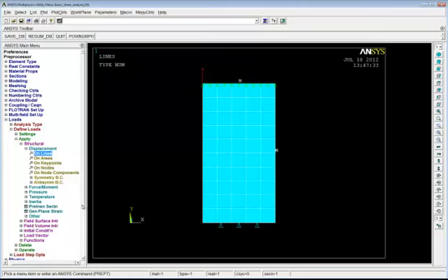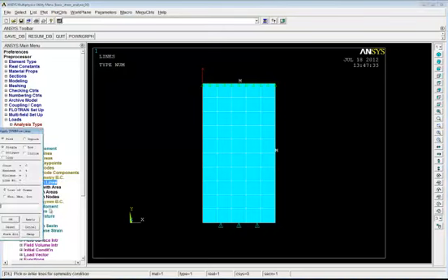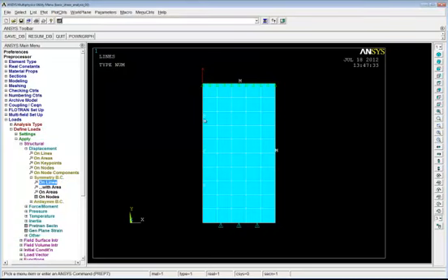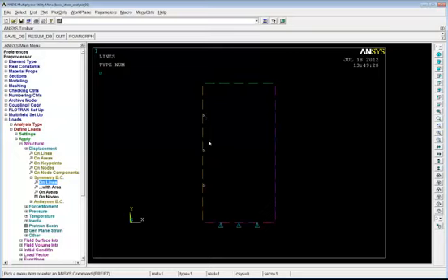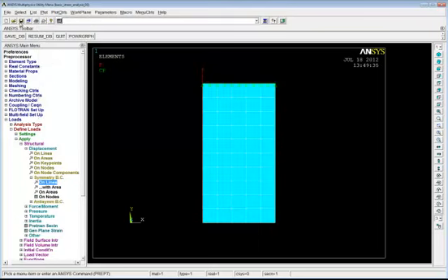Here's what's new. We now want to tell Ansys that this is a symmetry line. So we apply symmetry boundary conditions on lines. Pick that line, OK. And you might be able to just see that little s's have just come up there. Okay, so if I just plot lines, maybe we can see that a bit better. Yeah, so there's S for symmetry boundary conditions on that line there. Okay, let's just solve that, see what happens this time.